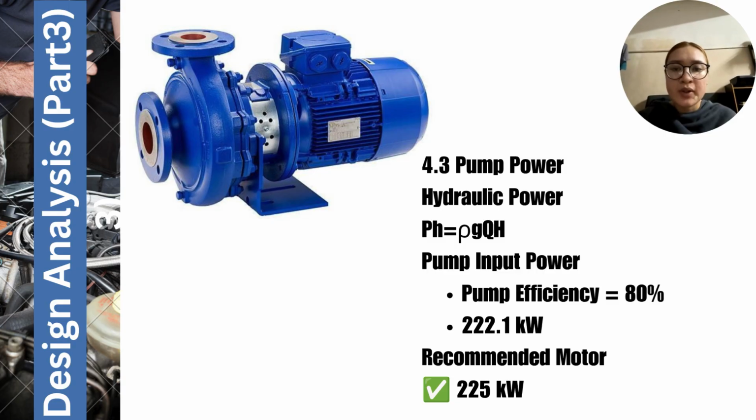The hydraulic power required is 177.7 kilowatts. Considering an efficiency of 80%, the input power increases to 222.1 kilowatts. Therefore, a standard 225 kilowatts motor is selected.